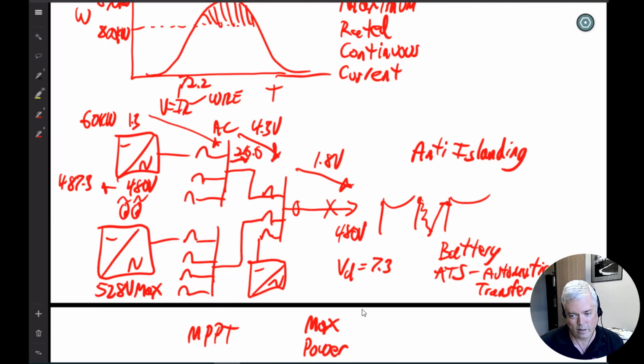And that's why you don't have any power, because batteries are expensive. Transfer switches, what we want to do is grid tie straight into the main switchboard and backfeed onto the grid when you're producing more than is required, and that's all there is to it. You're not trying to support anything, and so it's anti-islanding that makes that go down.